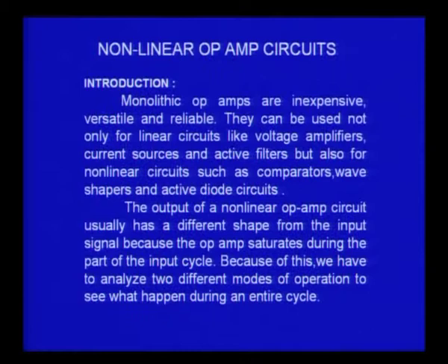One of the simplest applications that I can think of is how we can compare two voltages, whether which is higher in magnitude or lower in magnitude can be detected. Such application circuits are useful in many situations. We will perhaps take up some examples and applications of these circuits also at a later time. Because the monolithic op amps are inexpensive, versatile and reliable, they can also be used for applications which involve a nonlinear output input relationship.